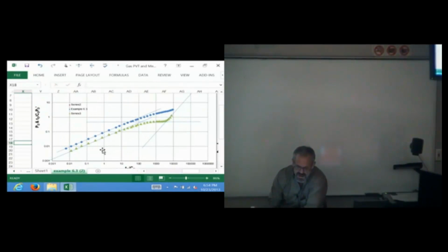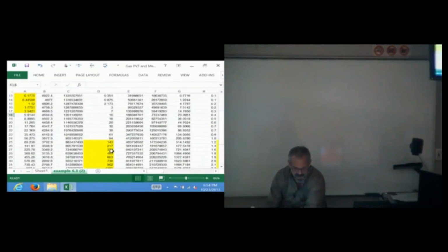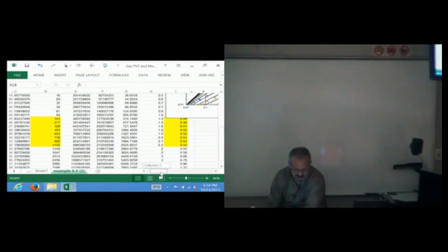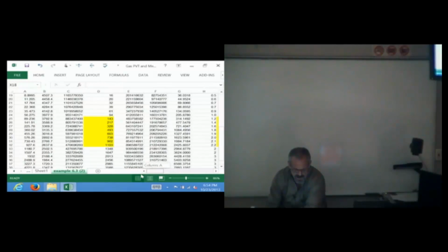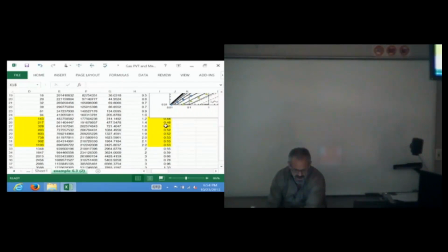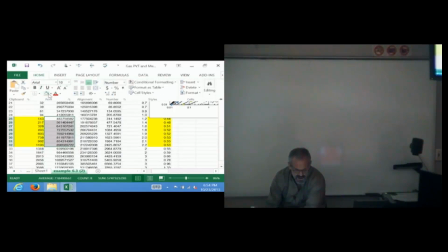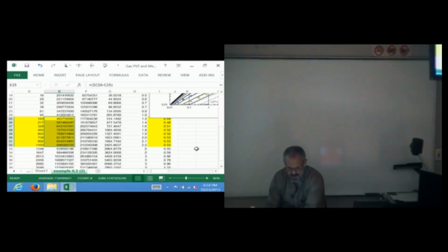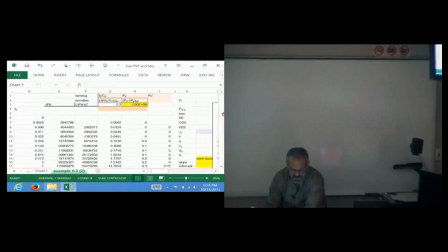Okay, so now let's crank out the analysis. All right? Let's crank out the analysis. We've already got a head start. I've already highlighted the data, time, and where our derivative match point slope is about 0.5, so we're going to want to plot pseudo pressure. Everything I'm highlighting in yellow should be part of my radial analysis. And we're already set up to do a radial analysis, right?